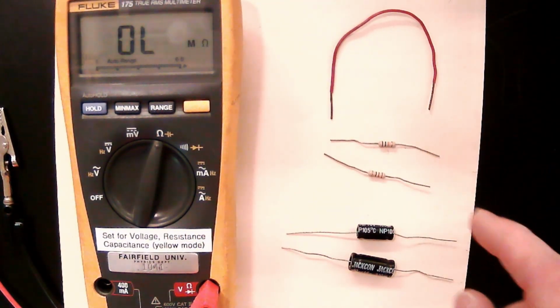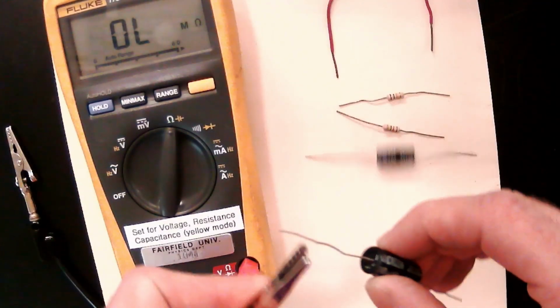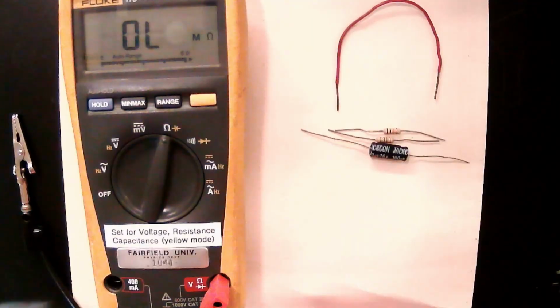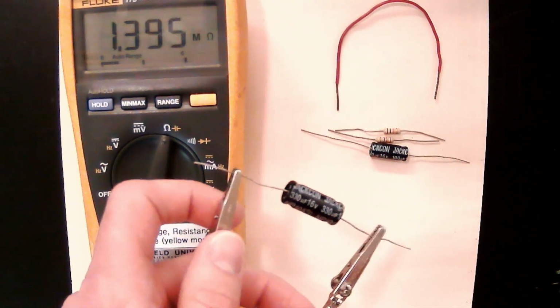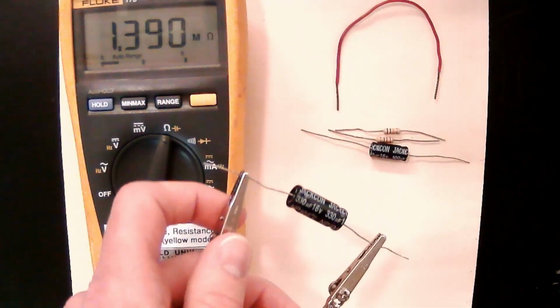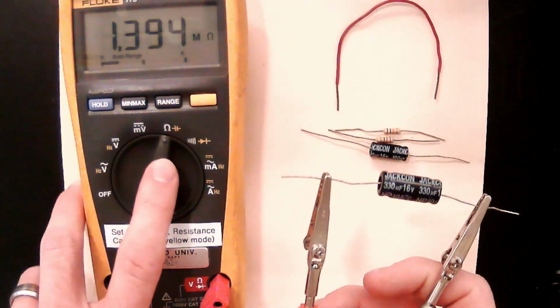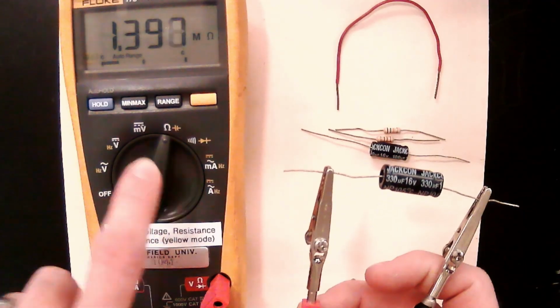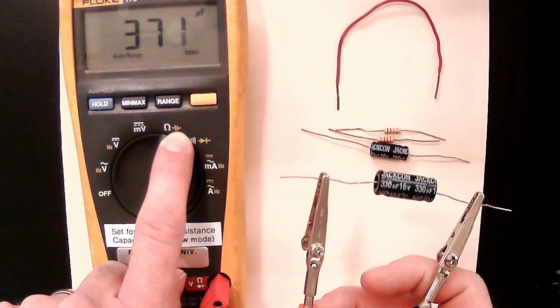And then, for your comparisons later, you can also figure out the capacitance of your capacitors, to treat these as your quote-unquote actual values that you will compare all your experimental data to later, right? To do that, stay with the ohm meter, but use the little yellow toggle button to switch to capacitance.